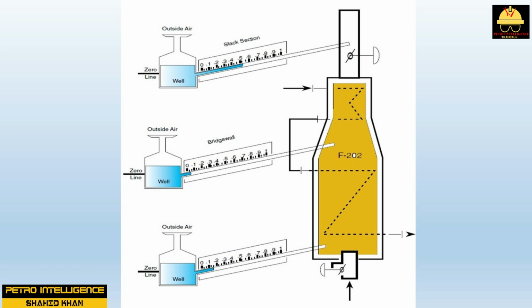Excess airflow will decrease furnace temperatures around the burners and force the automatic controls to increase natural gas flow rates to the burner, wasting money. As hot combustion gases rise, cooler air is entrained, causing the temperature to decrease. Excess air enhances this process.